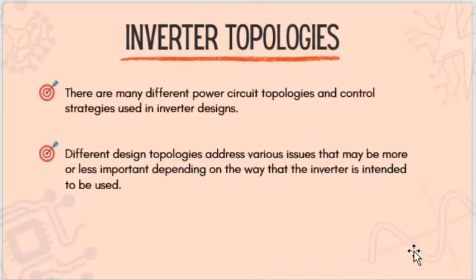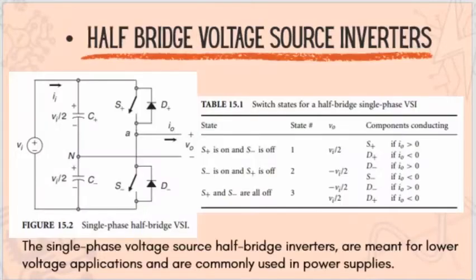Inverter topologies. There are many different power circuit topologies and control strategies used in inverter designs. Different design topologies address various issues that may be more or less important depending on the way that the inverter is intended to be used. First topology of inverter is the half-bridge voltage source inverter.